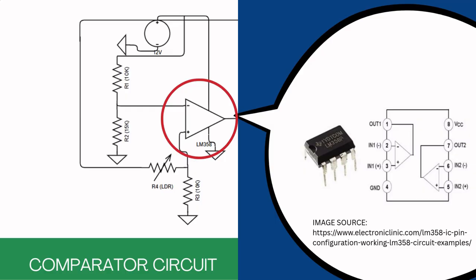And last but not least, the LM358, which serves as the comparator. As seen in the figure, this integrated circuit or IC actually consists of 2 op-amps, either of which can be used. In our case, pins 1, 2, and 3 were defective. That is why we used pins 5 and 6 for the inverting and non-inverting inputs, pin 7 for the output, while pin 8 for Vcc and pin 4 for the ground.